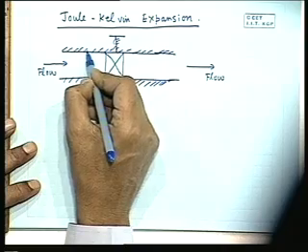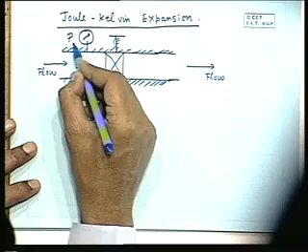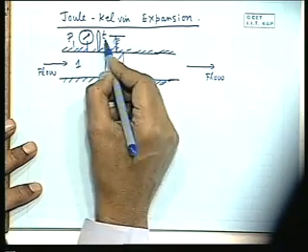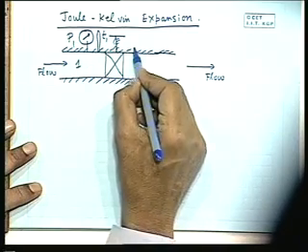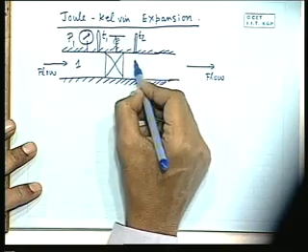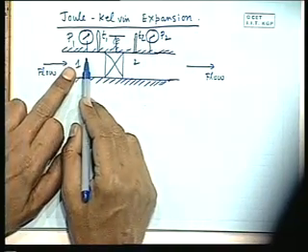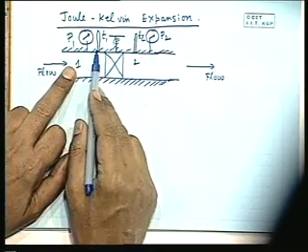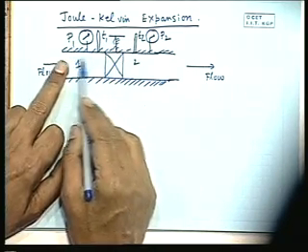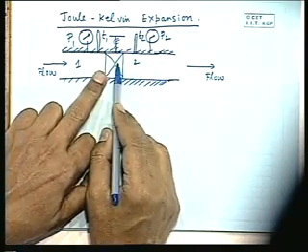That means if one keeps a pressure gauge here, let this section be 1, with pressure P1 and temperature T1, and in a similar way keeps a temperature T2 and pressure gauge P2 at station 2. So we place pressure and temperature measuring instruments at a location further upstream from the valve, where the stream is undisturbed, and again at a downstream location where there is no disturbance from the valve.